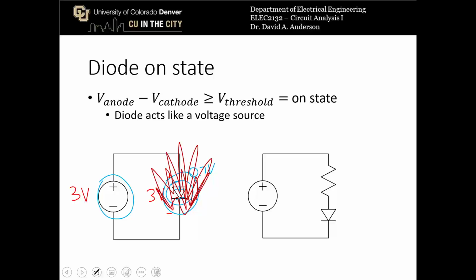Generally, when you connect two voltage sources in a circuit and something is wrong, like you can't connect them together ideally in a circuit, and you try to do that in real life, something is going to start smoking and burning. So we don't want to do that. In general, you never connect a diode to a voltage source without some series resistance. So let's look at that scenario now.